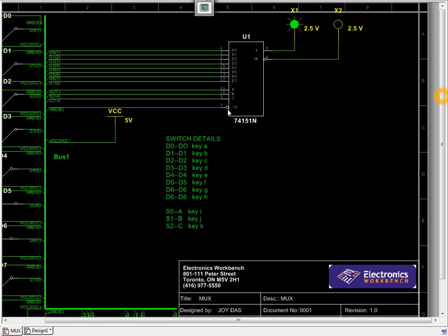That is said to be the enable pin, G here. You need to connect it to ground, as it takes an active low signal. If it hadn't been grounded, the IC wouldn't be in operative condition, and the outputs would not be shown properly. And as you can see here, I have used a simple bus structure to connect the inputs.